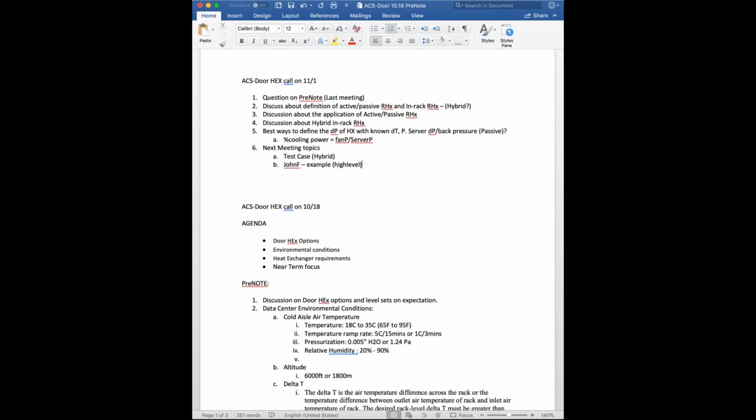So the sealing, the separation of intake air and outlet air within a rack, is crucial, because there will be a pressure point on the hot side and a low pressure point on the intake. Of course, and if the pressure drop of the coil is higher than the pressure drop of the, let's say, sealing, then we will not have success. True. But again, if we compare the difficulty that air has traveling through IT equipment in the small spaces to the air traveling through a coil of a back door.